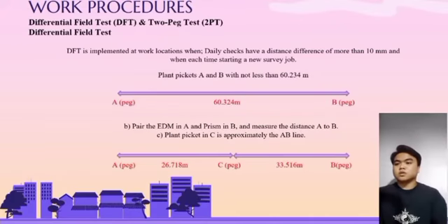Next, I will continue to present the work procedures for the differential field test and the two-peg test. DFT is implemented at work locations when daily checks have a distance difference of more than 10 mm and each time when starting a new survey job.